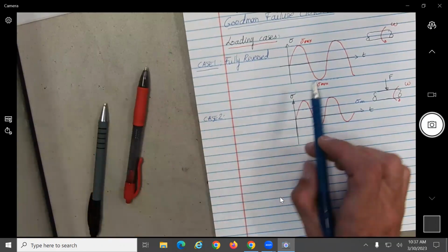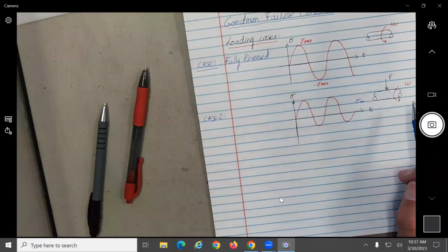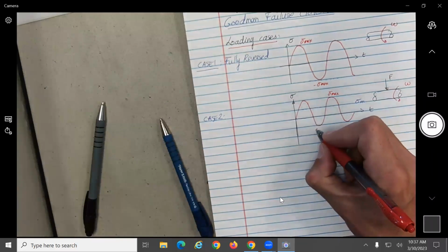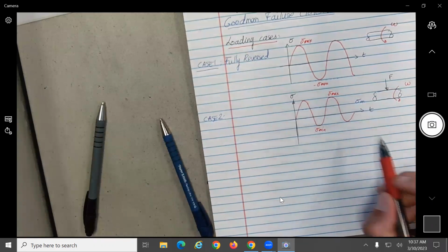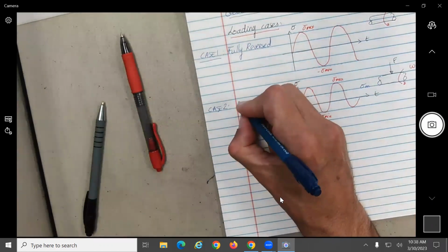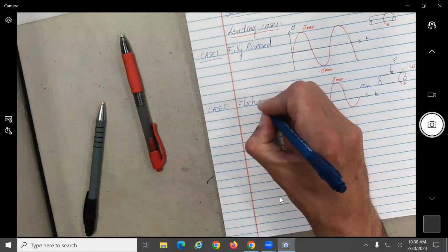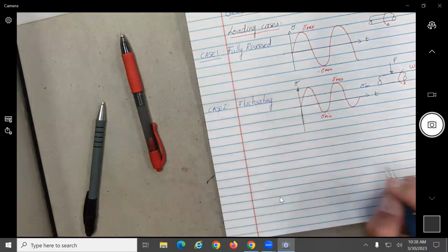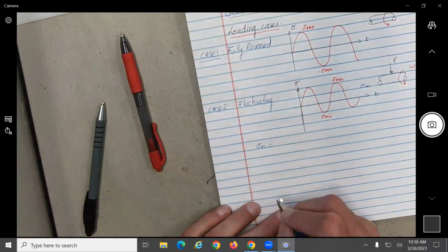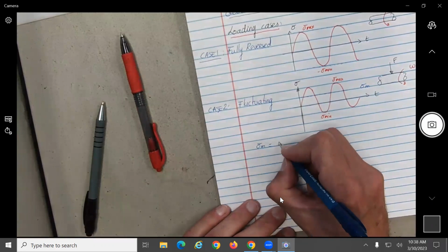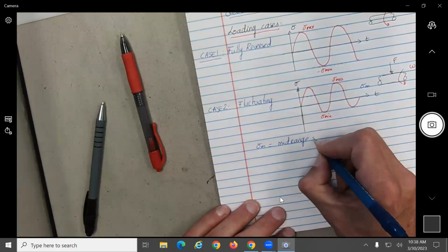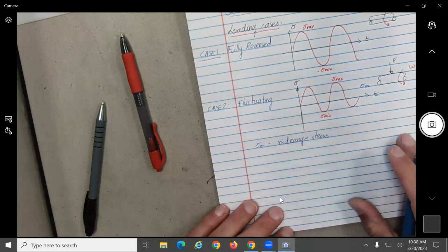Basically, in the previous case this is 0, since there's no external force, and here we have another one. So in this case, you see sigma maximum is not the same as the minimum, because you will have sigma m, and this one is called fluctuating. All right, so let's see. Over here, the sigma sub m, so the stress sigma sub m, is called mid-range stress.